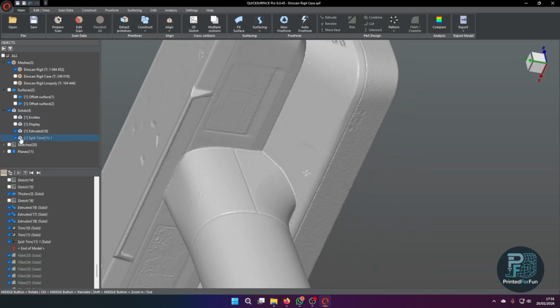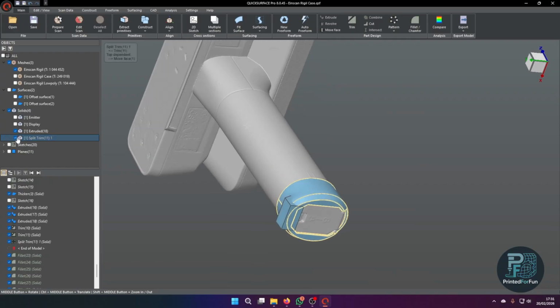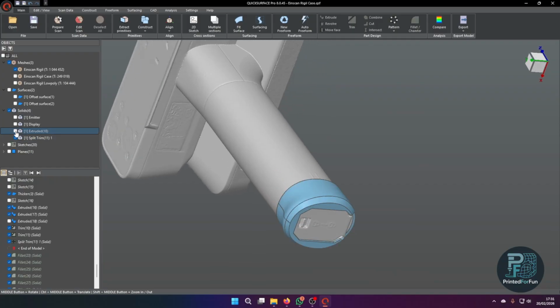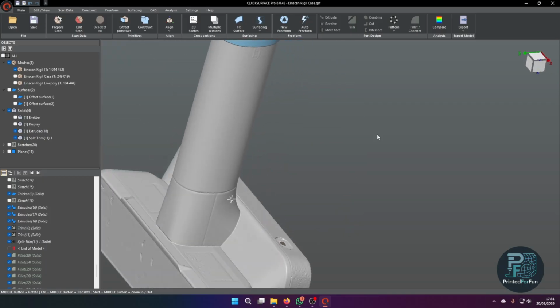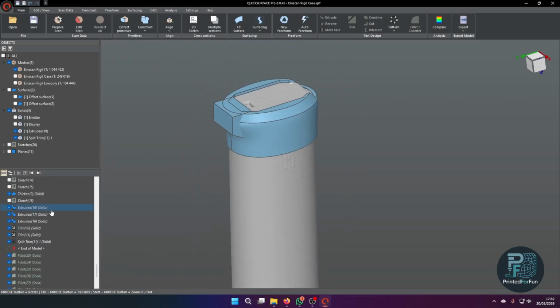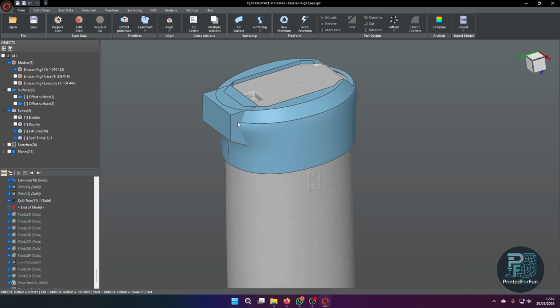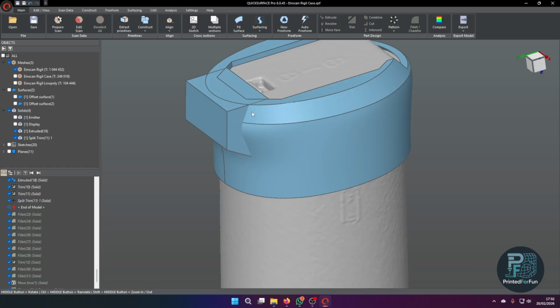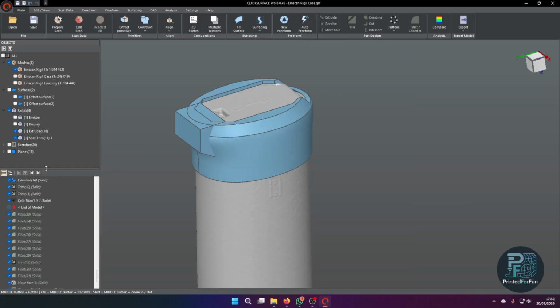As you can notice, at this step, I didn't combine these two surfaces together, because I first wanted to add all my fillets to this one before combining them. So this often makes filleting a bit easier if you're not having these very sharp intersections here that could cause problems.